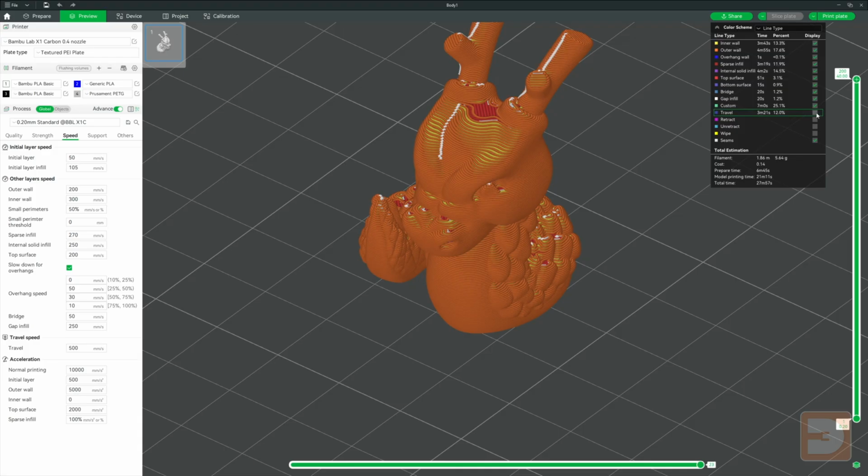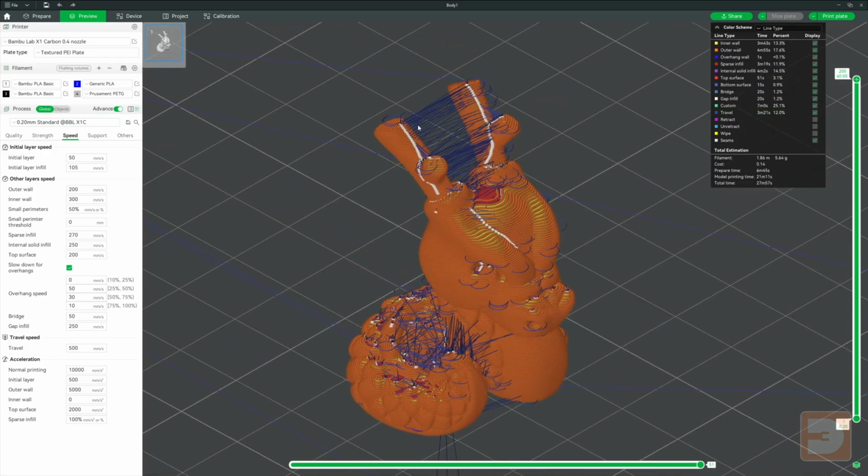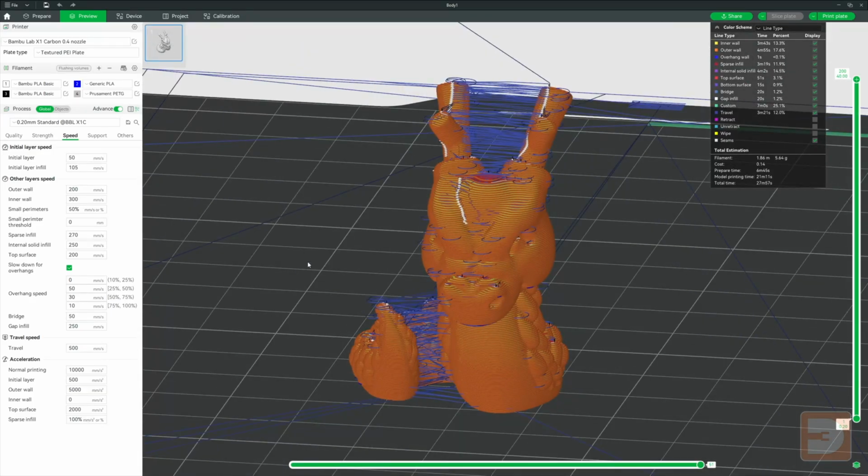Those are the speeds that the printer will use when actively printing different parts, but as we saw earlier, the printer will also need to move when it's not actively extruding filaments. The next setting we have is travel speed. This is the speed the printer can move at when it's not actively extruding. It can obviously move much faster when it's not printing, as it doesn't need to be able to melt and extrude filament to keep up with those speeds. However, the faster it goes, the more vibrations it will create and the bigger potential for lower accuracy in the print. If your printer is listed in the configuration wizard when you first set up Bambu Studio, rather than having to enter all the specs for your printer manually, this is likely set to a decent speed that your printer is capable of without affecting quality, so generally it can be left as it is.